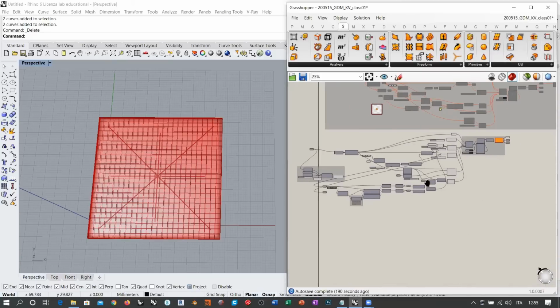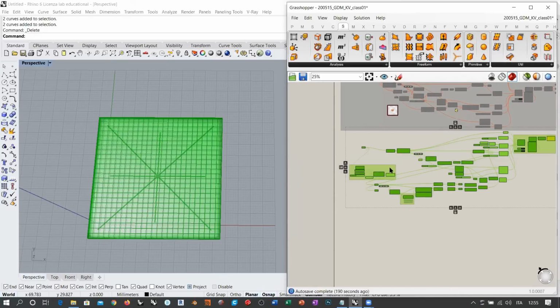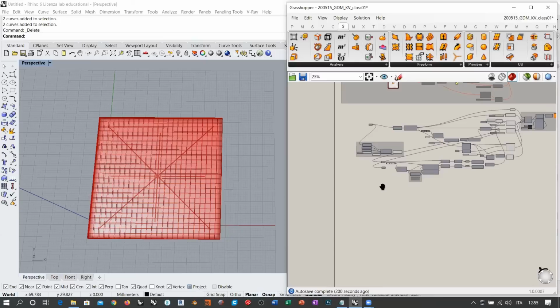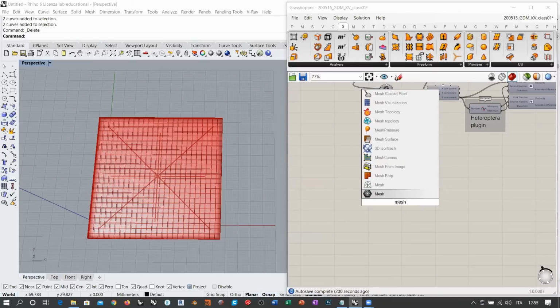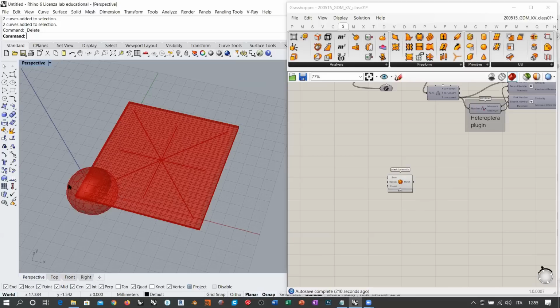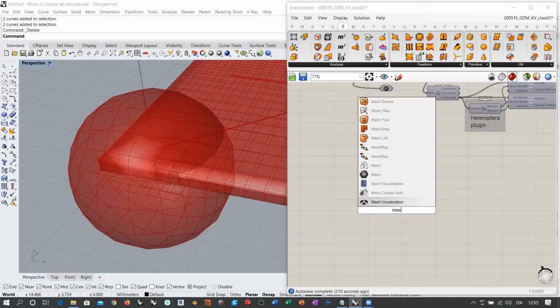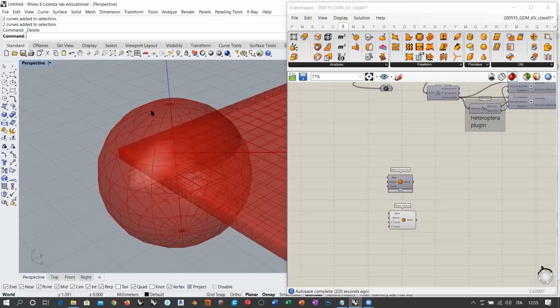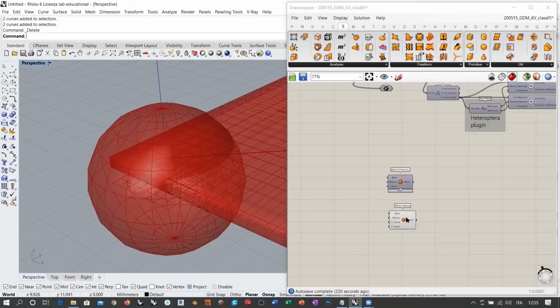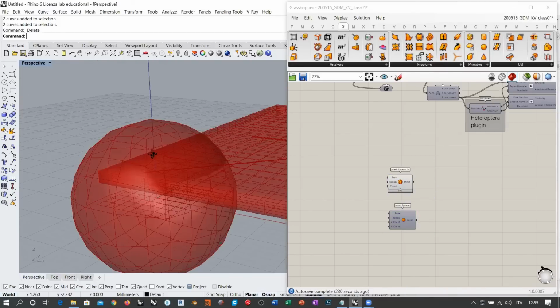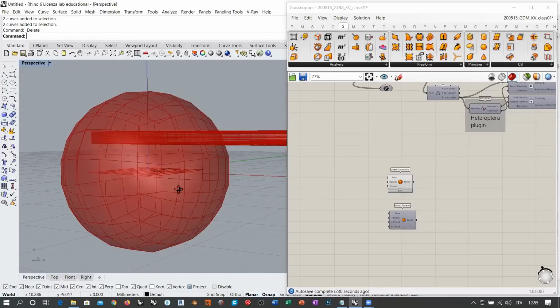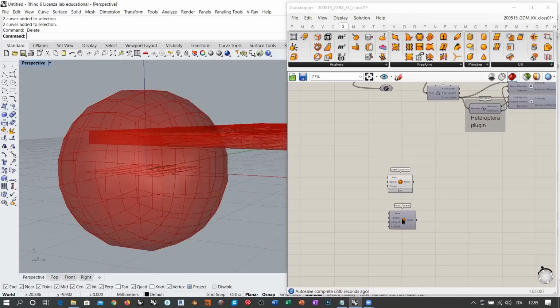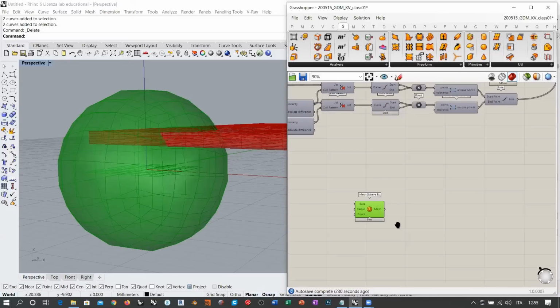There is a particular reason that affects all inflatable structures in Kangaroo, which is this one. What I'm going to do is take a simple mesh sphere, but not the mesh sphere, the mesh sphere X, because its topology is a little more regular than the normal mesh sphere that I'm going to show you. The mesh sphere is based on the UV division, so it has poles, okay, while the mesh sphere X is basically an inflated cube. So as you can see, that's the cube topology, but it is inflated, okay? So I'm going to take this and convert it into a balloon, for example.